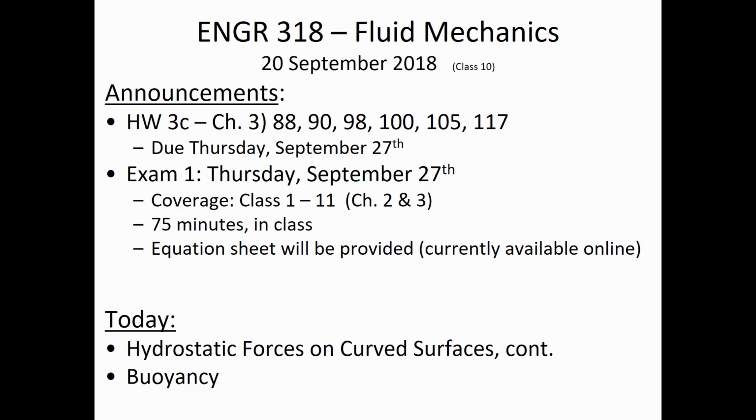So once we come up with what that vertical projection looks like, then we go through the same process that we did for flat surfaces. So we ask questions like, what is the depth of the centroid, delta H? What is the orientation of that? Well, it's a vertical projection, so luckily our delta H is going to be equal to y bar.